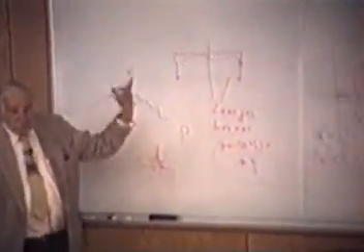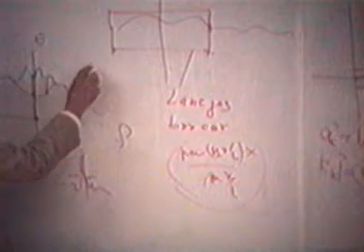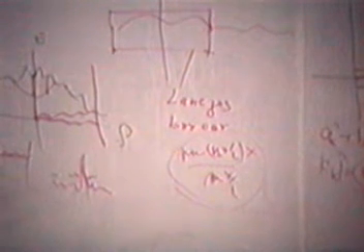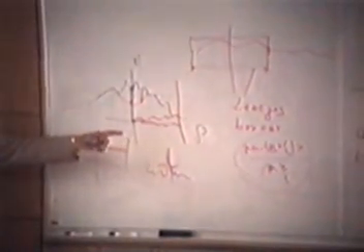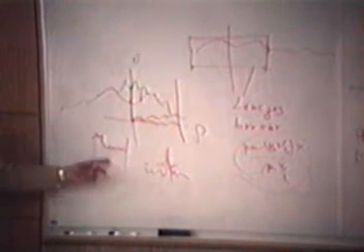Now I sample. Bing, bing, bing, bing, bing. I'm aliasing, right? Now the original one had a spectrum like that. Once I alias, those are folded back and forth, and so what I see is not that spectrum, but I tend to see something pretty flat here and something there. That's what I will see because of two effects: the finite length, which smeared things out, and the aliasing, which brought it back and forth.